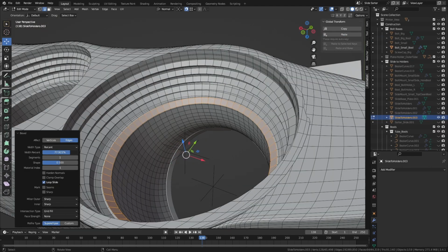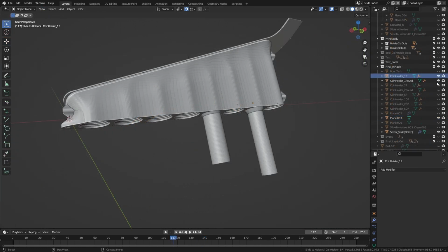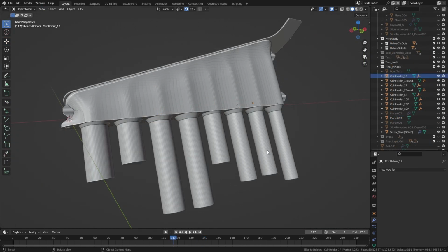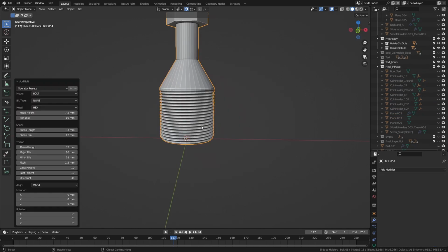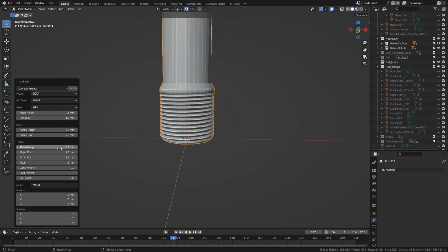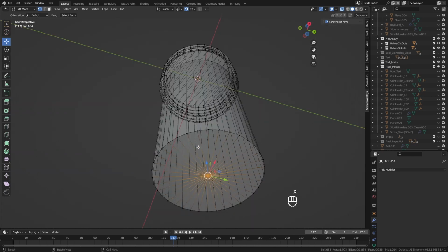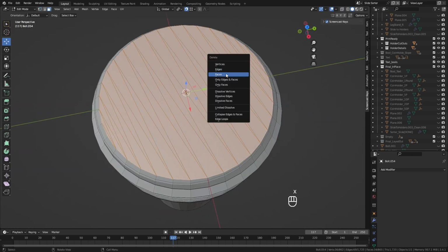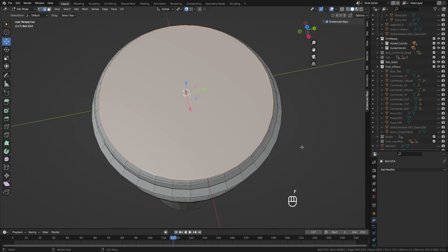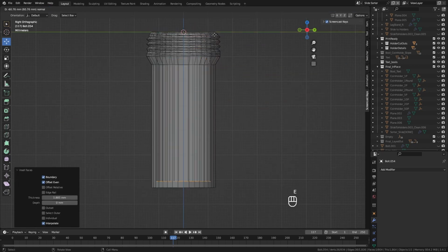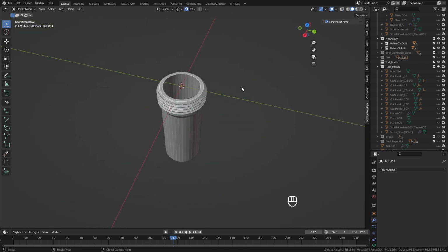it was done. The last parts to create were the coin holders. I used a bolt mesh as a base for this, changed the sizes, and set the thread length to 10mm. In edit mode I then deleted the bottom and capped it off, went to the top and deleted these faces. Filled with a single face, inset and extruded down. This was the base of the coin holders.